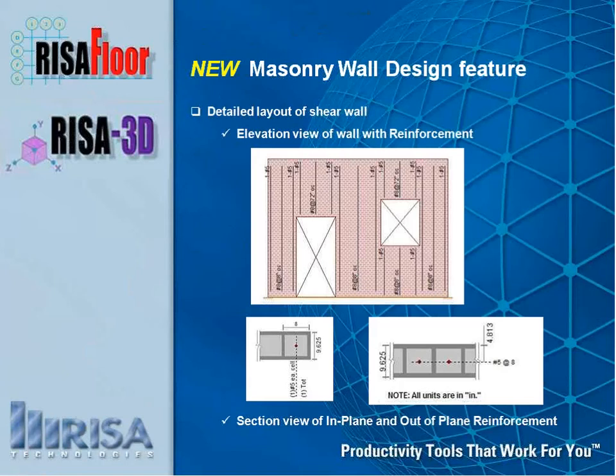Also, at the end of all this, we're going to get the design. We really want to be able to see what this wall looks like. How do we detail it? And what we're looking at here is a picture of what the detailed view looks like. So we're going to have an elevation view of the wall with reinforcement on it. We also get section views in plane and out of plane, showing us the reinforcement there. We're going to see that in the detail report. So we have a nice way to actually view this and see it after the fact once we design it.